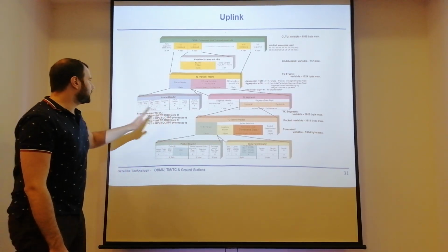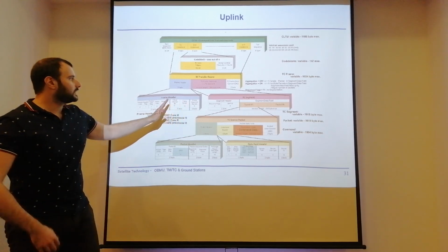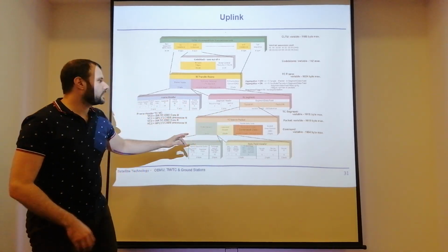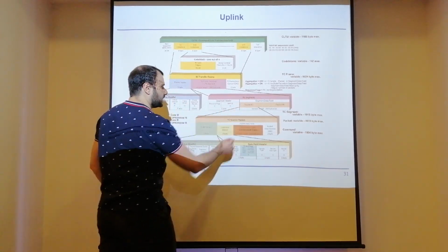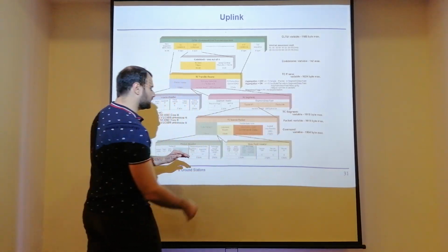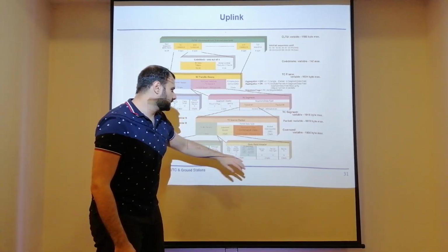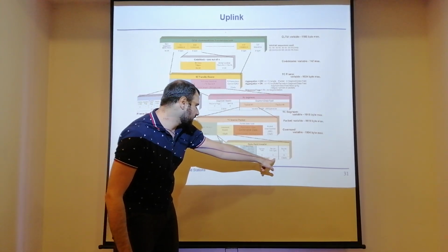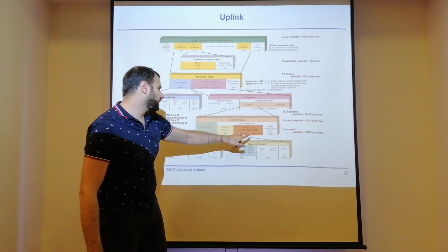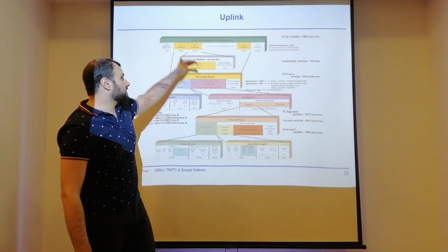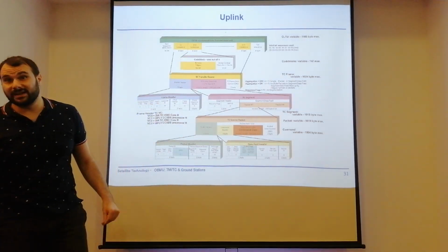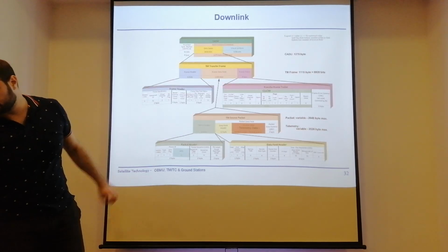Then we have several fields in our frame header and also in our TC segments. And finally, we go to packets, and each TC source packet is again equipped with a header and a data field. Finally, here we have our data included in the command data. So this is how we go down to the data level from the CLTUs.